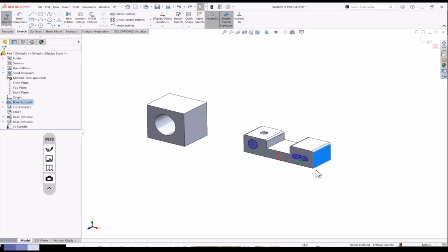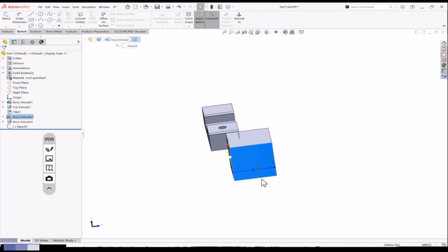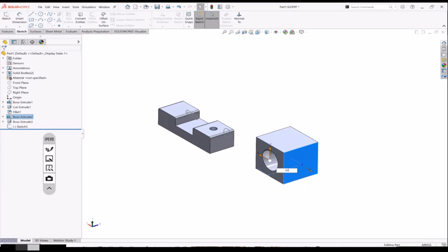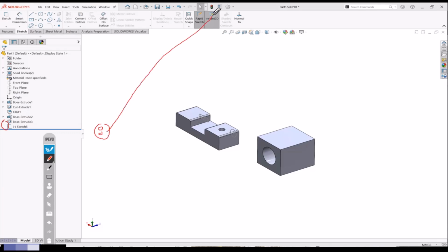What is Control B basically? Suppose I try to make changes. Sometimes if you make changes in the model, it does not update. Let's try. It's 44. Let's make this 50 and click. It changed actually. If it does not change, I'll tell you what will happen. There will be one green and one red dot symbol that will come on that particular command, which has not updated on modification.